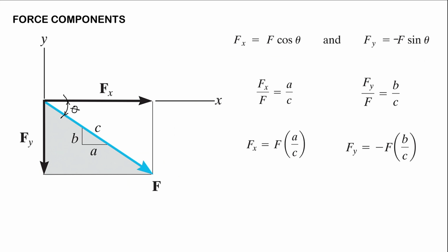Right, so there's another way of solving this, which we will be mainly using when dealing with trusses or inclined members. So we have here a slope triangle. This slope triangle is similar to this force triangle. So we're just going to be using ratio and proportion.